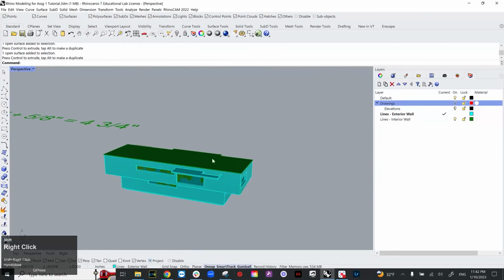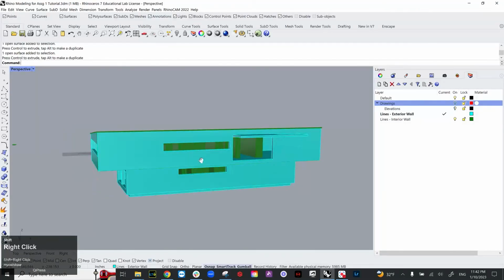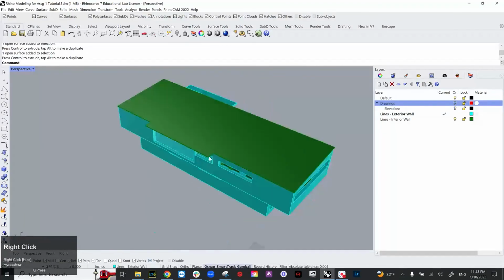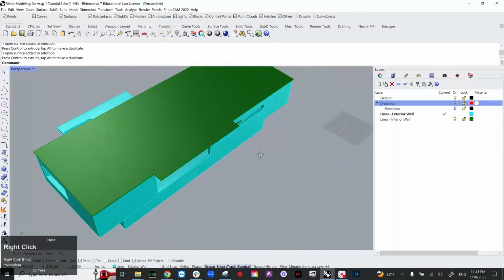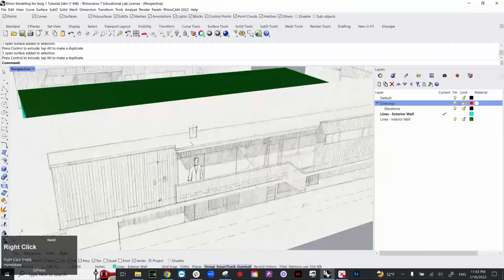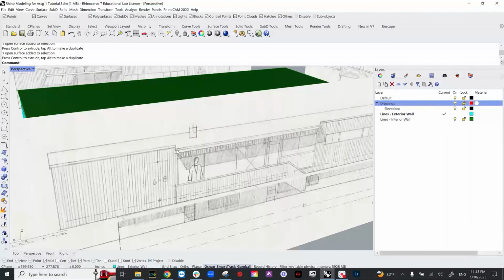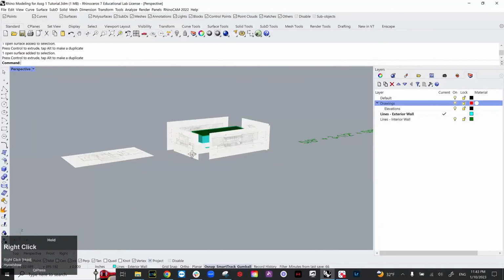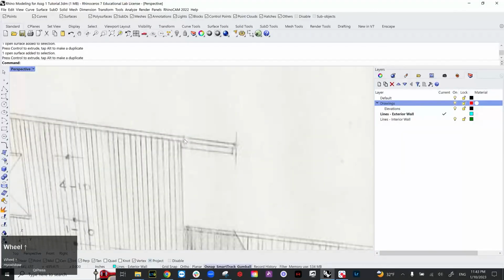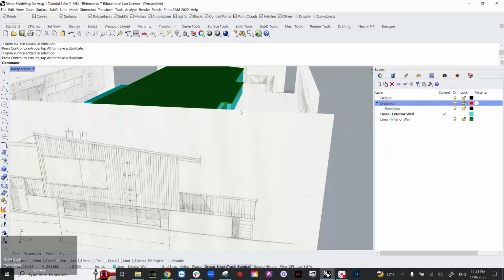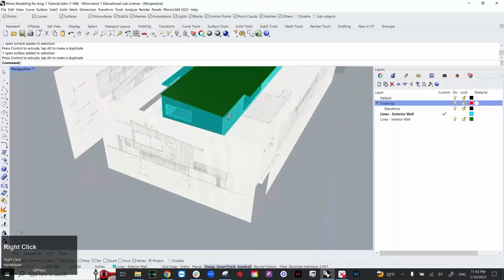Okay, so I punched open all the windows for all the sides of the building. I also adjusted the roof shape. While I was looking at the drawings, I realized that in this elevation, the roofline is jogged over here, which indicates that this portion of the roof is coming out. And that is sort of confirmed with the side elevations as well. So there's a straight line over here, which indicates a straight line over here. And then this portion is what we see in the elevation over here.